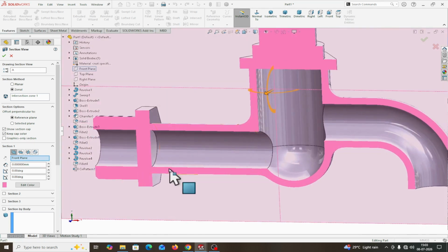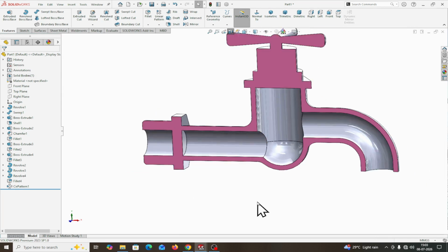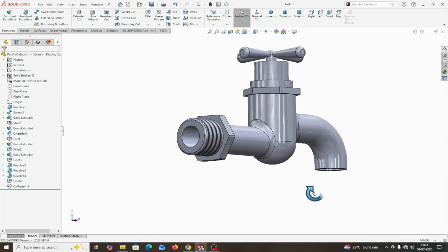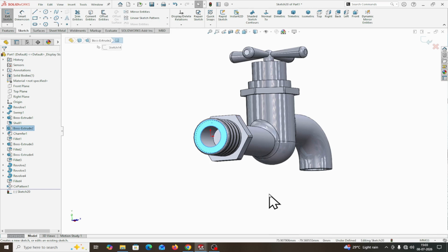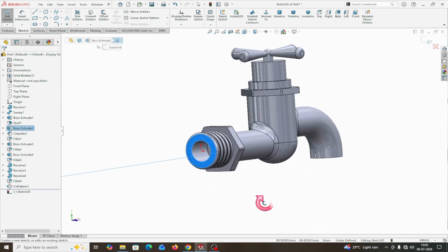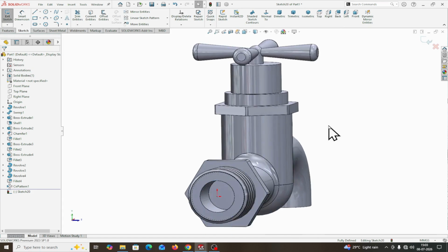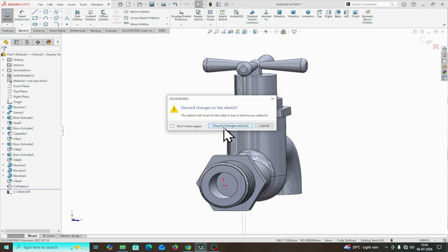One thing, you can also make this portion hollow actually, this internal part. How you can make the hollow here: select this face, sketch, and this is total 30, sketch, normal, convert entity, this convert entity. Okay, I make this one.